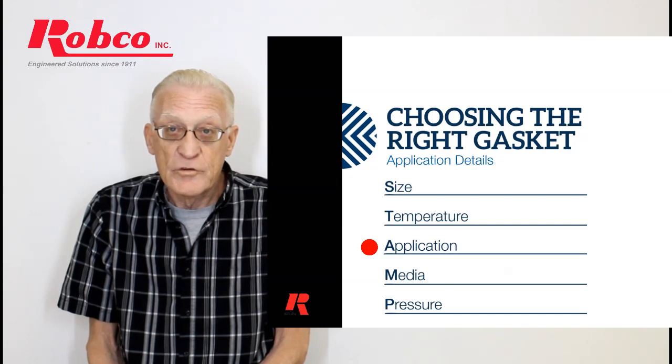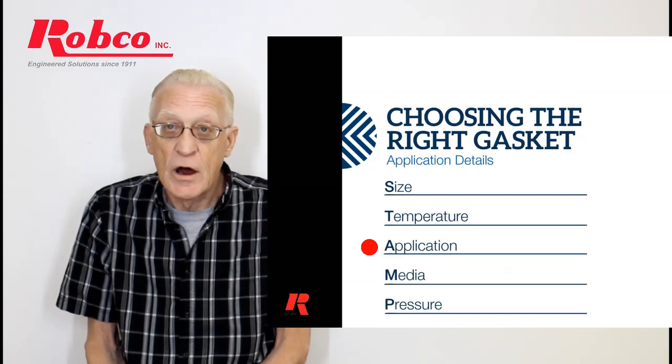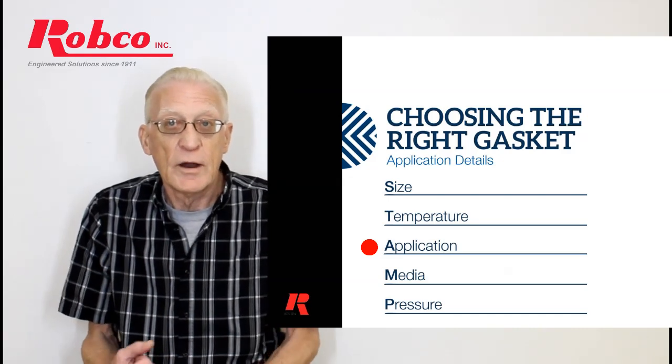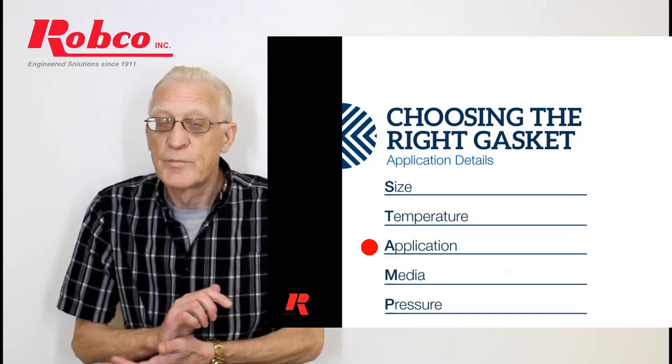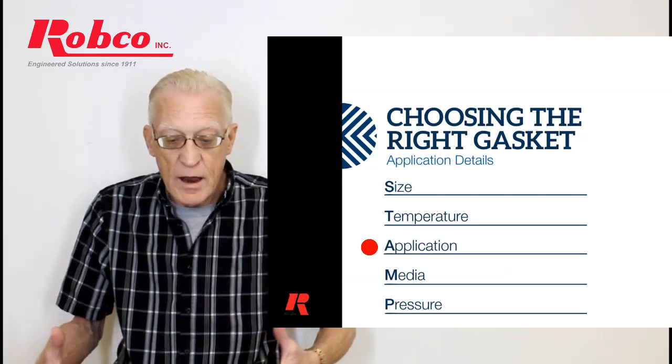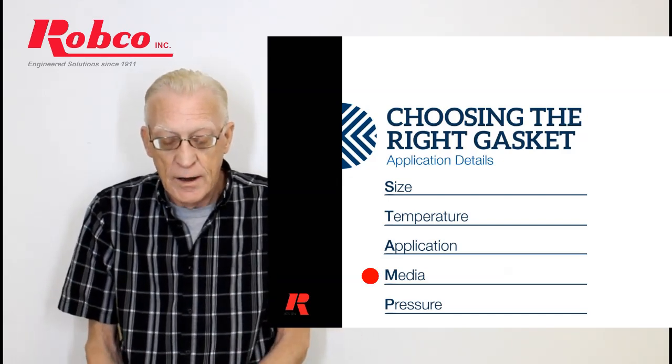Application is what we're talking about. Application is not the temperature, the pressure, the media, etc. We're talking about how many bolts do you have, what are those bolts made of, are they lubricated or not, etc., etc. The actual junction of the gasket.